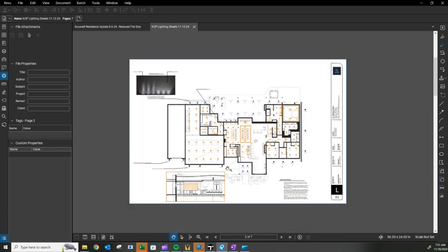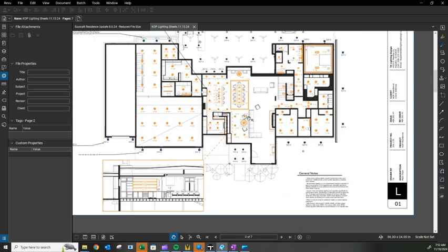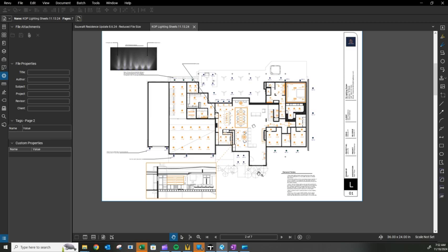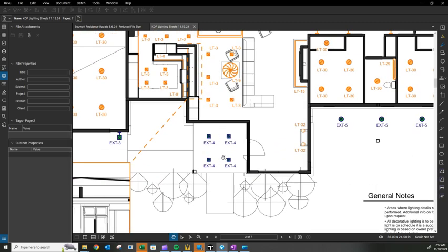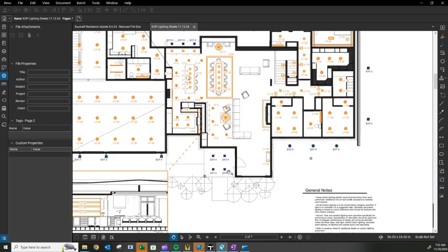Cover sheet, and then here's the lighting plan based on that visualization and that photometrics. We have a lot of the notes in there, and everything we do is we show lighting placement and the types, so you know which type it is, because a lot of the lights are performing a different function. They have different mounting, they have different optics, so that's why they have different types made. They have a different exterior rating, where one can be interior. In here, we're doing all dim to warm. Everything else is static white. So those are definitely different types than these would be right here, because that's a focus in the house where they want it to look really nice and feel really nice.